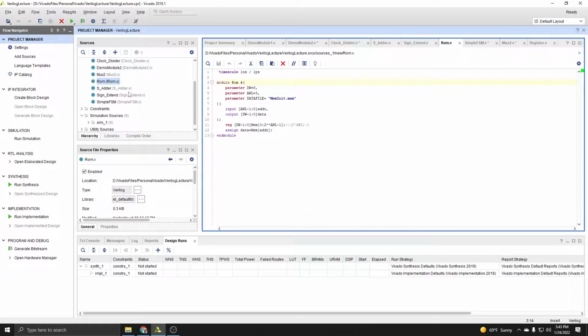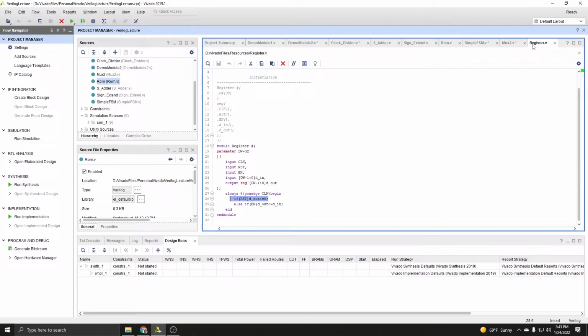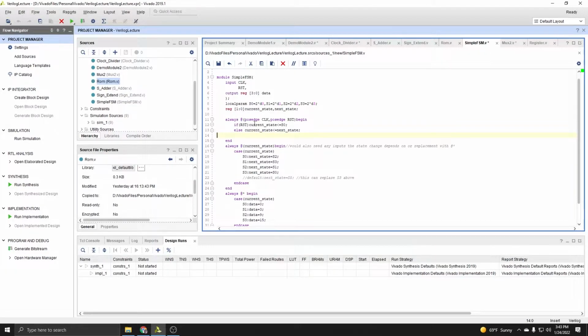So you're going to see a bunch of X's. If that value is assigned to something like a register, you can almost get away with it, because if you just assign a value, then it's a known value. But with finite state machines or any other kind of sequential logic, you cannot get away with it because it will not know where it starts. If there's no reset in this finite state machine, there's no way for it to determine the next state, because it doesn't even know what state it's in.